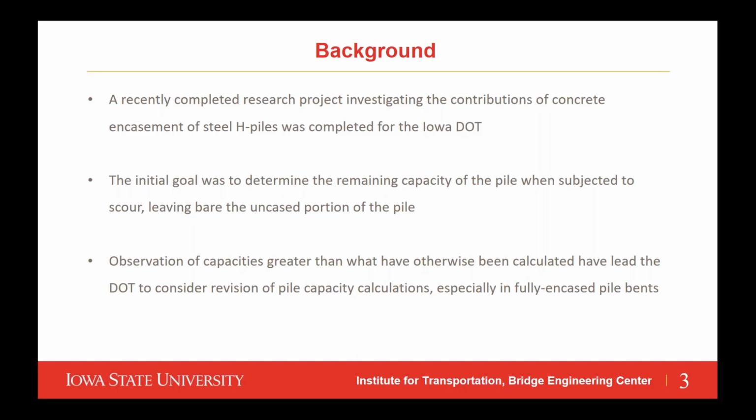What we observed in our previous study, both in an analytical and laboratory portion, is that there's a fairly significant amount of capacity in their standard designs that they're not taking advantage of, especially in the case of fully encased pile bents.